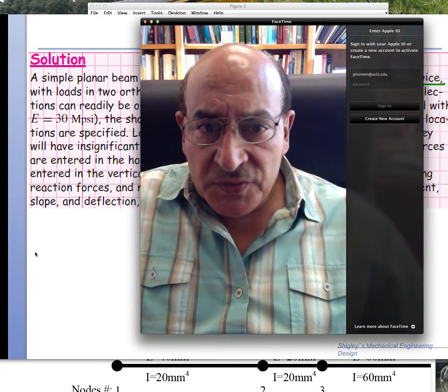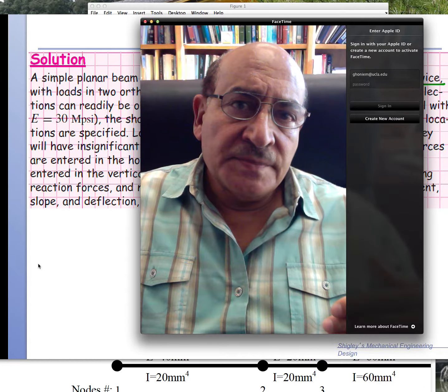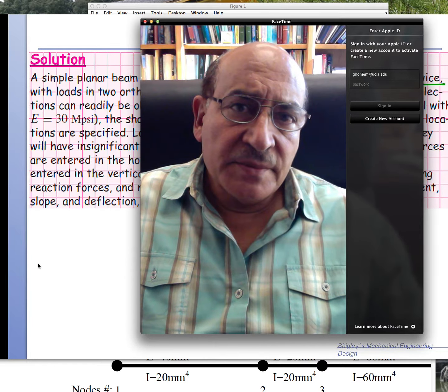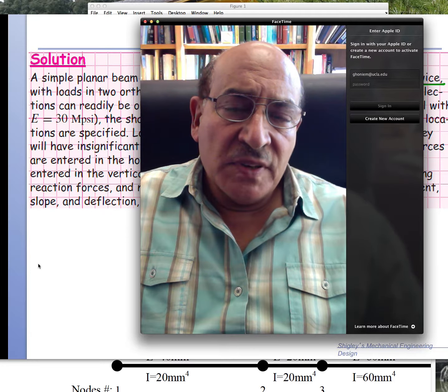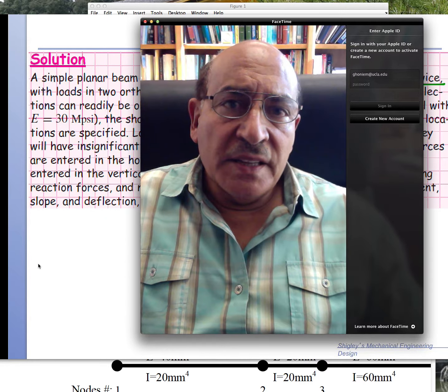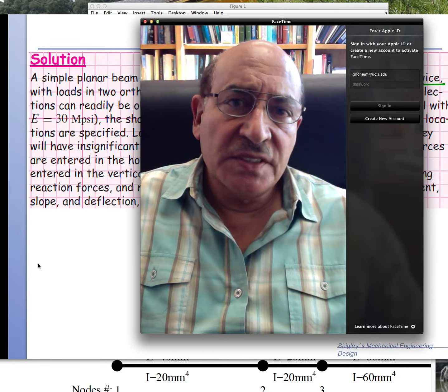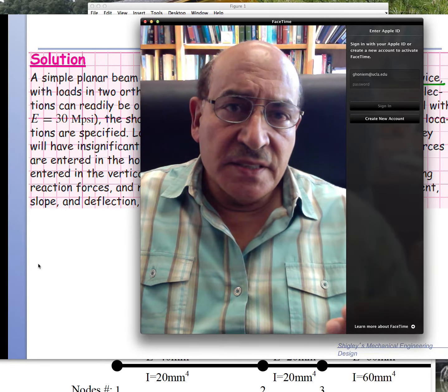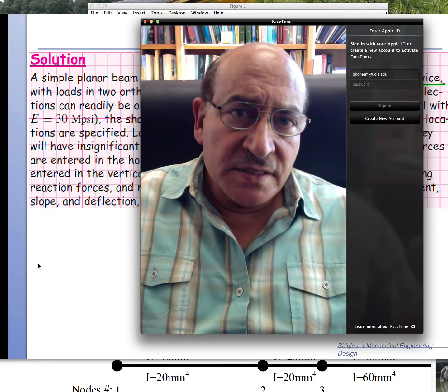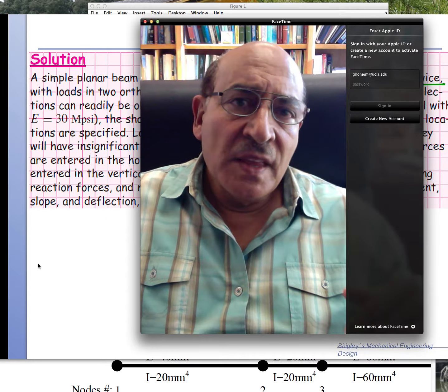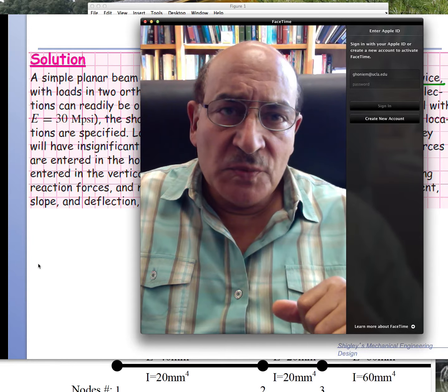If we want to discuss it, first we have to find the shear force diagram from the reactions in the XY plane and XZ plane, and then we integrate that to get the moment distribution diagrams. Since the forces are concentrated, the shear force diagram will be constant in between different regions of the shaft, and then the bending moment diagram will give us a linear distribution of moment.